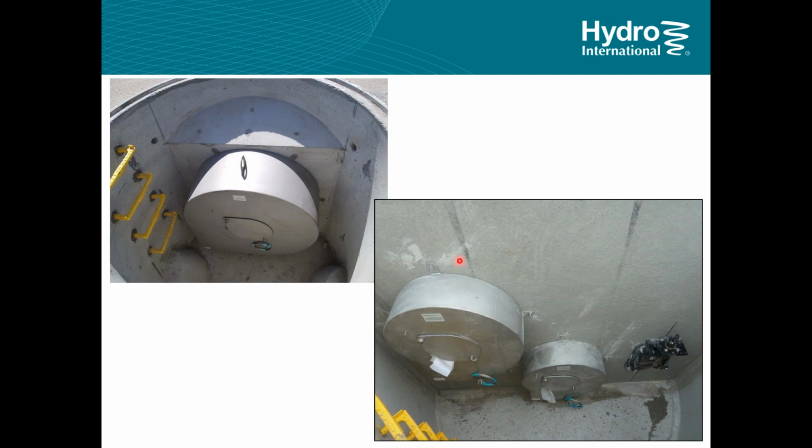And also, it's possible, when we do designs, often you have a 5, 10, maybe a 50-year release rate, and you would stack orifice controls and model that. You can do the same thing with the valve. It's just a head discharge curve. You can stack the head discharge curves in your modeling software, and you can model valves in stacked conditions. Okay.